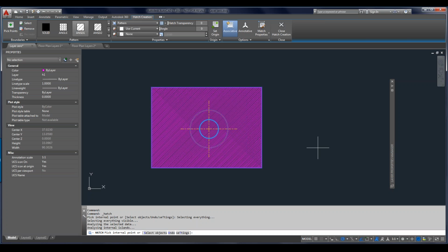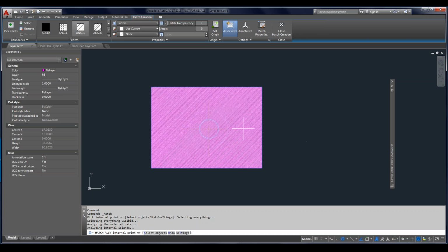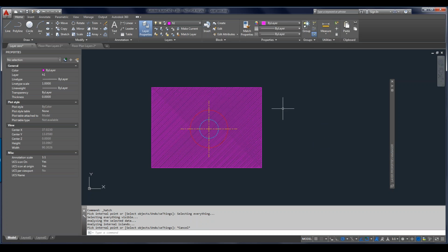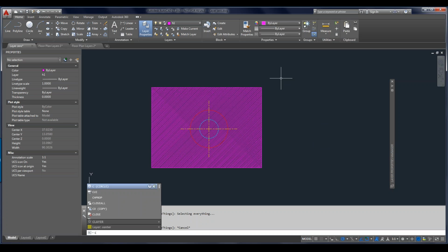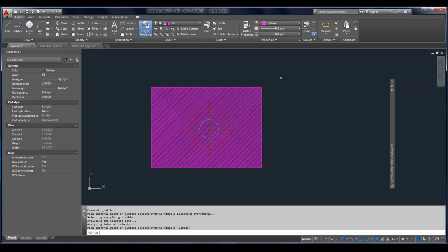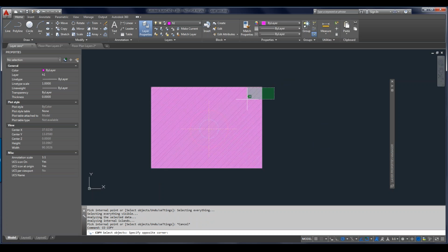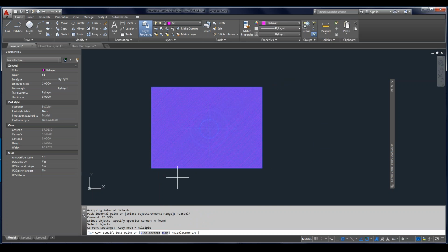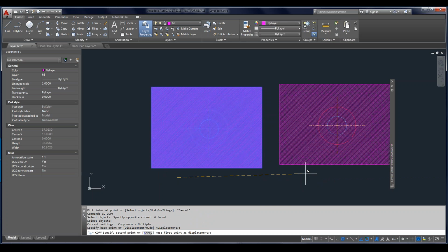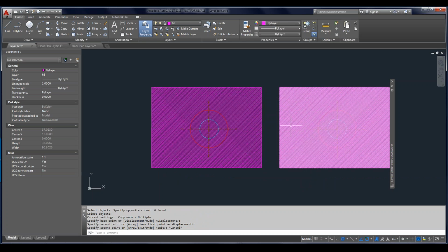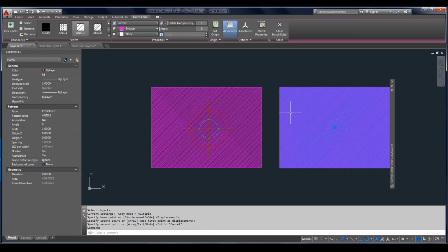So you've got grading maybe on something, or you need to have this hatch here. We do have options to send this to the background, and in AutoCAD we can actually apply a transparency to an object itself. Oh, there we go. Fingers are twitching here, sorry people. Okay, but we can also make things transparent by layer. So I'm going to go ahead and just select this, and I'm going to change the hatch on that one to layer 2.